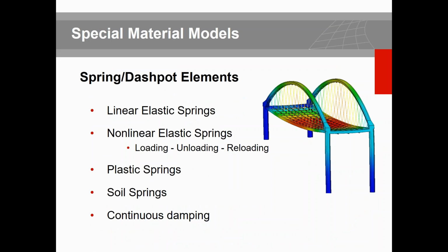You can interact and intersect different types of element types by means of springs and dashpots to mimic the interaction by means of linear behavior, nonlinear behavior, plastic spring, subgrade reactions, and nonlinear dampers that you may consider for bearings, for instance, when the bridge deck sits on the bridge pier cap.